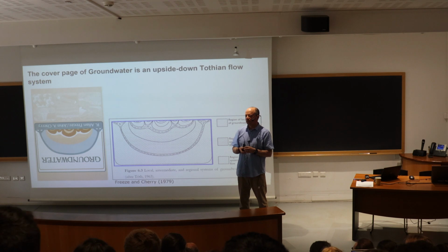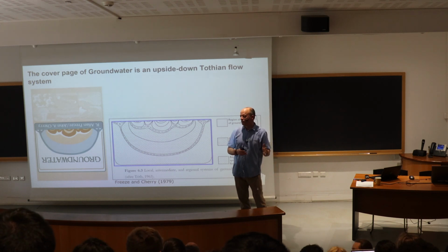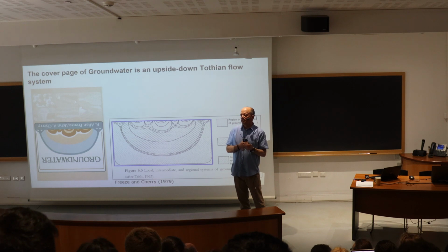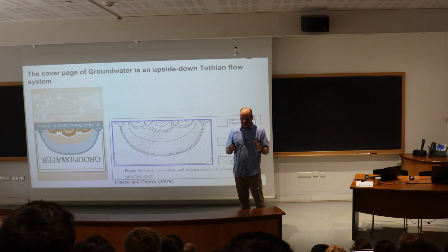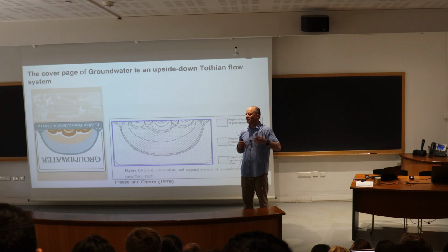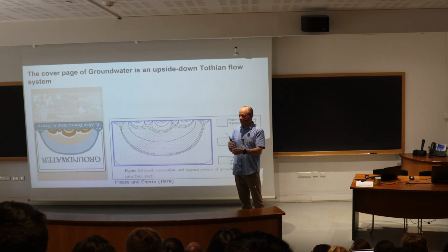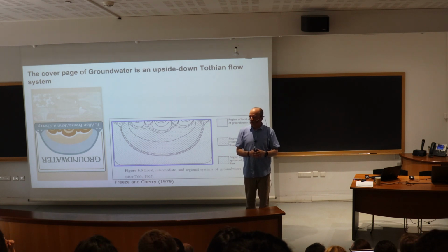Yeah, you probably will hear about dispersivity in the next presentation, I assume. And dispersivity is, okay, there's this concept that it increases with scale. But dispersivity really arises from heterogeneities. And if we were able to represent at a very small scale the heterogeneity of a system, say at the field scale, you want to simulate transport of a contaminant over 100 meters, and if we were able to have such a characterization that every square centimeter or very small volume you have the hydraulic conductivity, you put that into your model, you will not use values of dispersivities of meters.